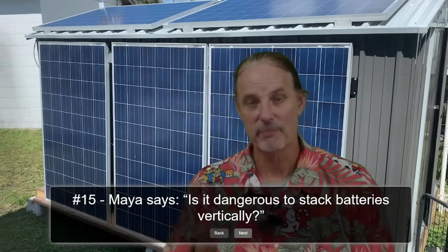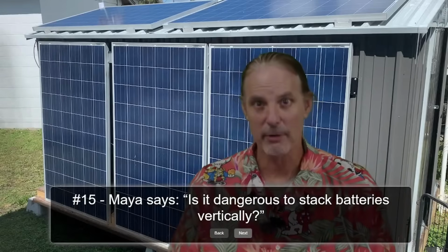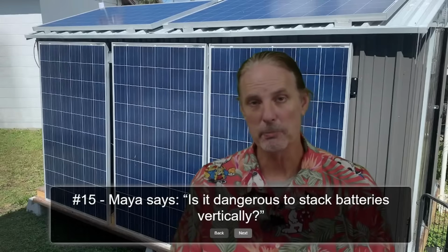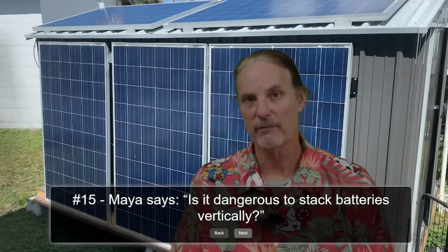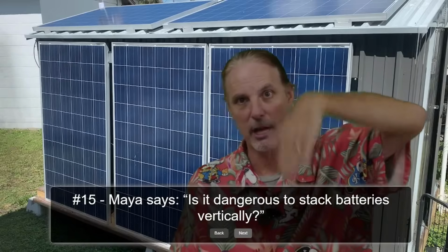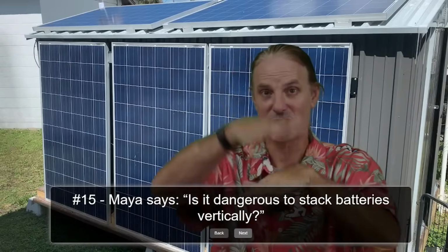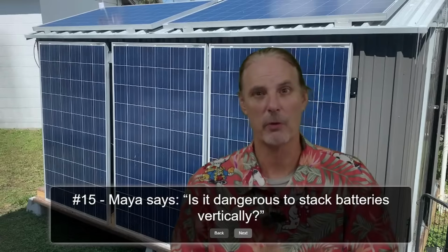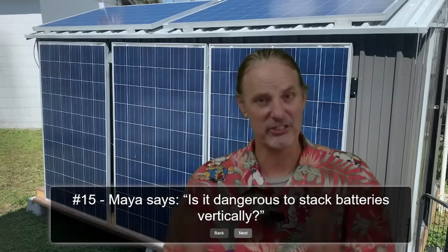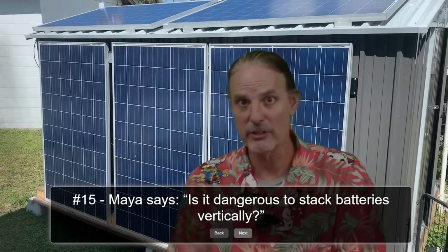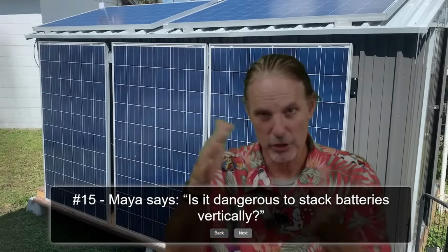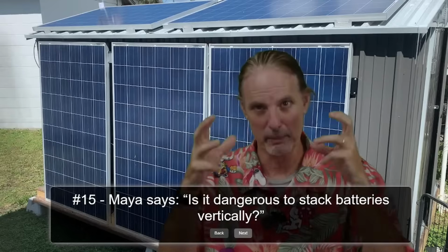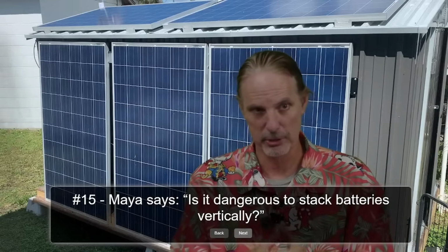So you do need to be very careful of the battery manufacturer specs of how those batteries can be laid. Most lithium iron phosphate batteries, it doesn't matter if they're sitting up or on their side. As far as stacking them on top of each other, that is a completely different question, and you would want to check with each manufacturer because the cells themselves matter, the batteries matter, and the way the batteries are built are going to make a difference in this particular case.